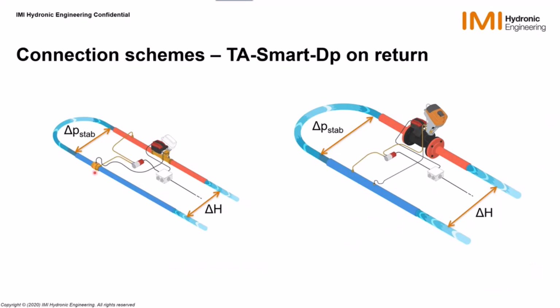In the small version, you get one temperature body for the remote temperature sensor, that's clear, and therefore I can go with my capillary on the bottom of it. It's easy to connect. And then on the other side, I get my capillary connected to a special adapter. We will see what it looks like, but it's basically an adapter from half inch to be simply screwed onto an extension that would have been soldered on the pipe, and it's quite standard to be able to go into half inch. And then this adapter itself has a female G1/16 space to screw in the second capillary.